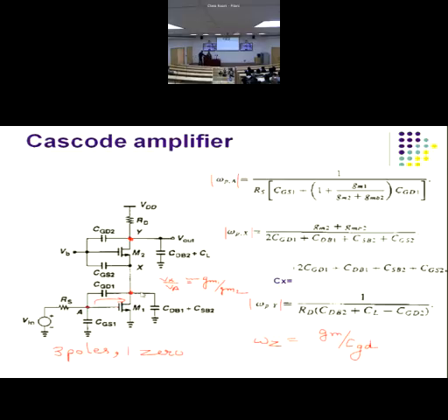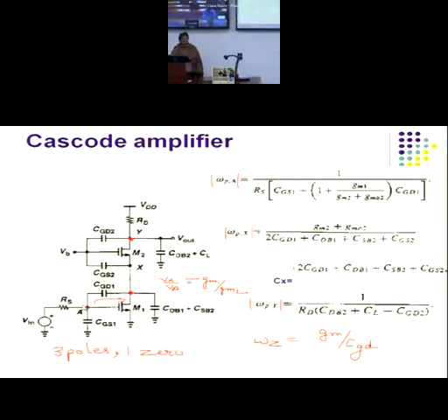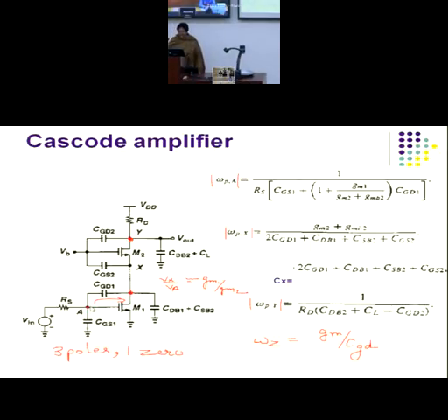So between A and X, now actually your signal path is from A to X to Y. Okay, so this is our main signal path. You have to keep this in mind. So anything that comes up in the main signal path is of interest to us. Okay, we need to analyze it and we need to thoroughly check it. So as I said, as we move from A to X, here is a Miller component CGD1. I will call it a Miller component because it is existing in the signal path, though it is not directly between A and Y. But it is coming in the main signal path, so I need to take it.